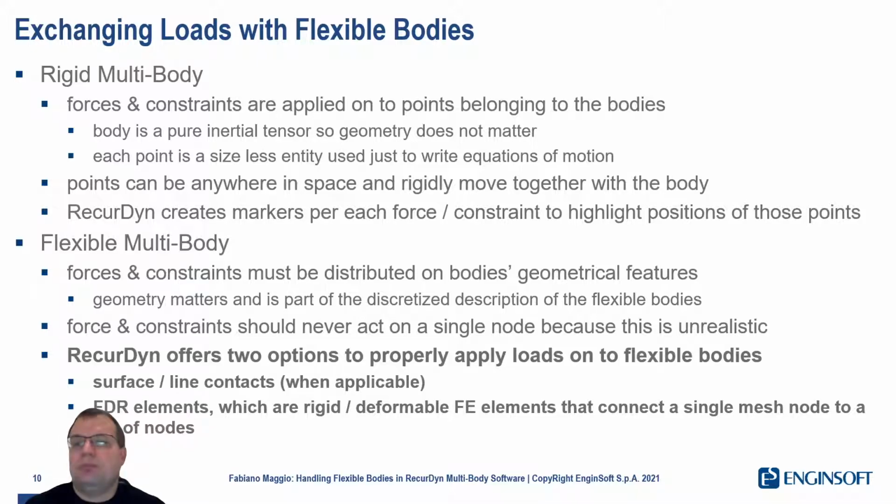If you use a load applied on a single node of a flexible body, you will have local effects that are completely unrealistic. You cannot do that. You can do that in rigid multibody because there is no deformation, but in flexible multibody, it doesn't make any sense.